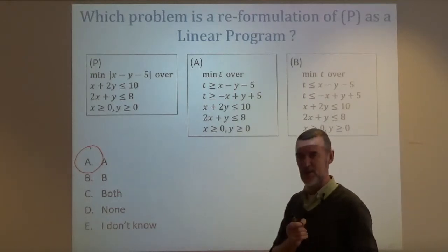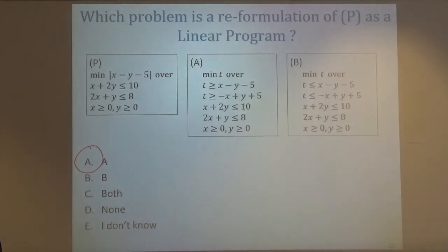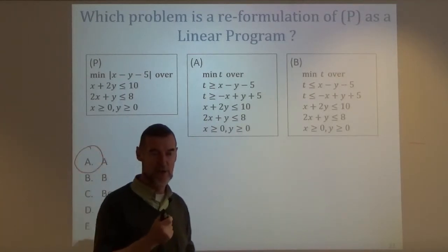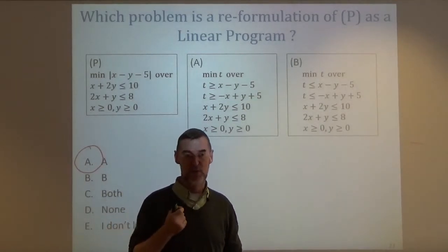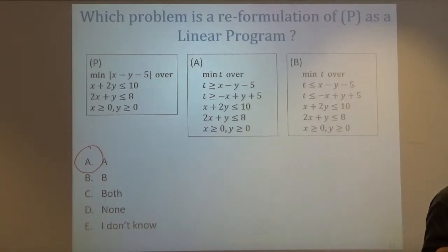Our problem as energy or smart grid specialists is to model a physical reality and find an operational solution to a problem. So the formulation of the problem is often part of our job, more than the solution, in fact. But we have to know which kinds of problems are easy to solve. And the best and easiest problems are the linear programs. So if you can make your problem linear, do make it linear. And one trick is to replace squares by absolute values, for example.